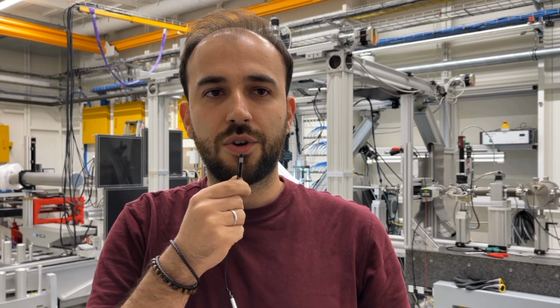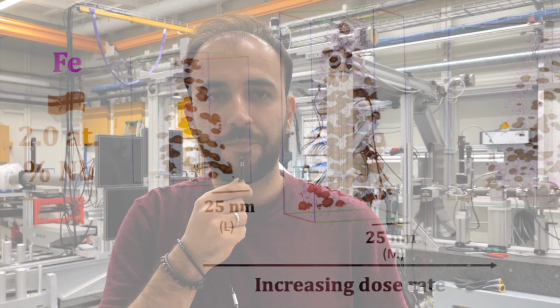While the investigated dose rate difference did not produce any significant changes in Zircaloy-2 through synchrotron XRD dislocation density measurements, it was found that the highest irradiation dose rate produced comparably higher dislocation density in Low-Tin ZIRLO. However, the latter alloy was found to have drastically smaller dislocation density compared to Zircaloy-2 in each dose rate condition after 0.15 dpa nominal proton irradiation damage.